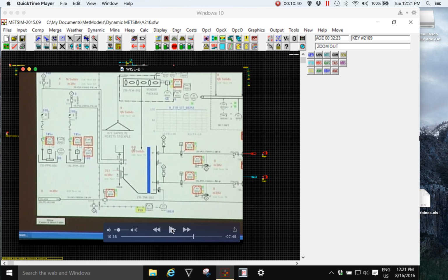And the METSIM capabilities for dynamic modeling go as far as you would like them to be. So as I said, in this case, there is a pseudo pressure network with flow distribution according to downstream valve positions. Tanks overflow, pumps can break, valves can have characteristic flow conditions, etc.